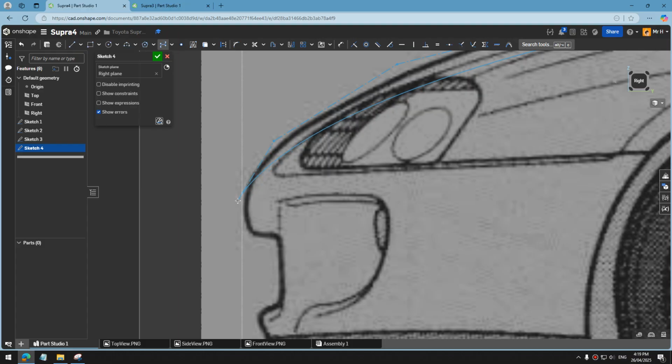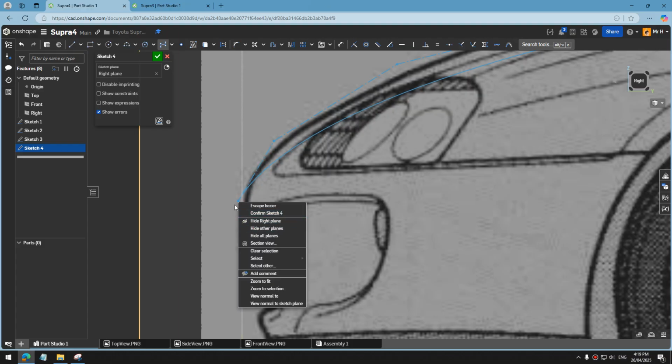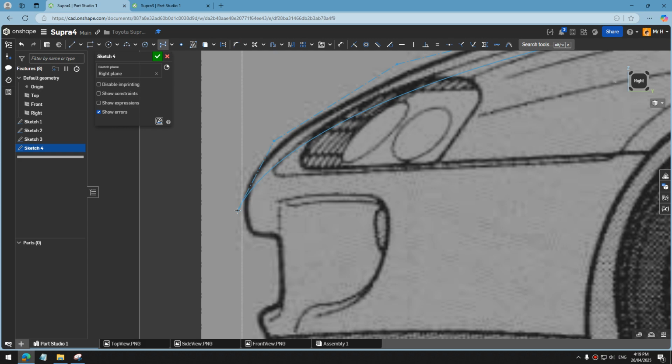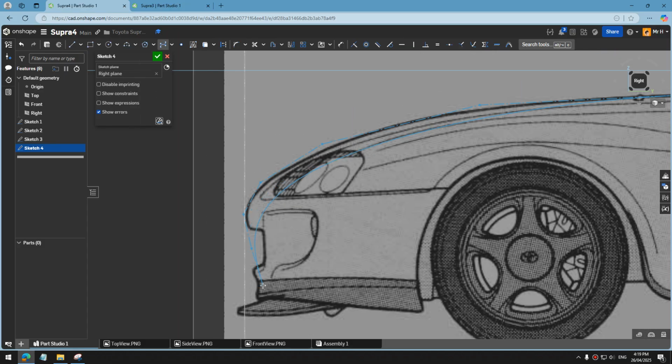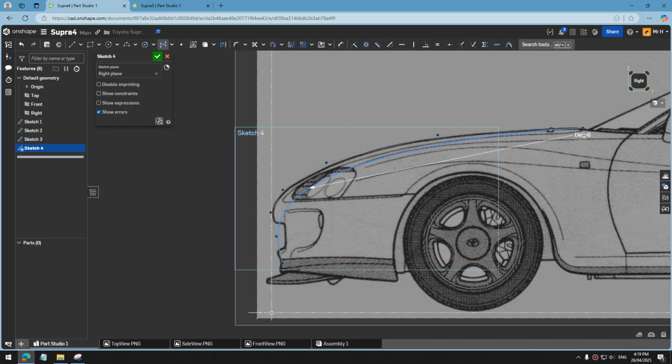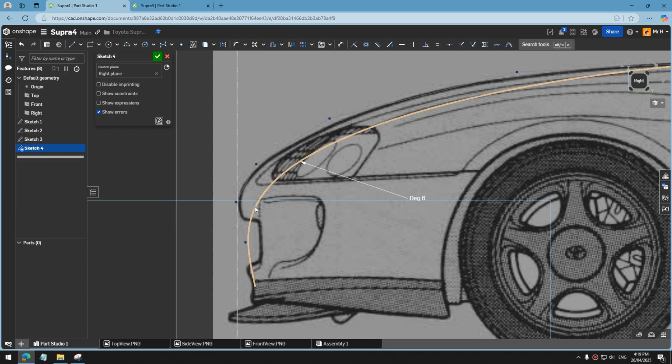And if you hold control, it tries not to snap onto there. Alright, let's click away. Let me see, shift or control. If you hold shift, it doesn't snap anywhere. Alright, and we double click to finish. Alright, press escape to go out of the curve tool.